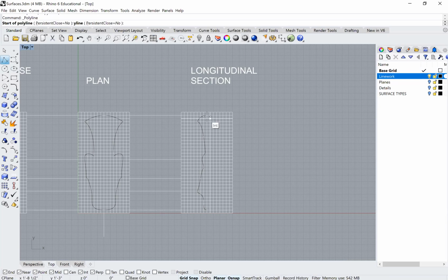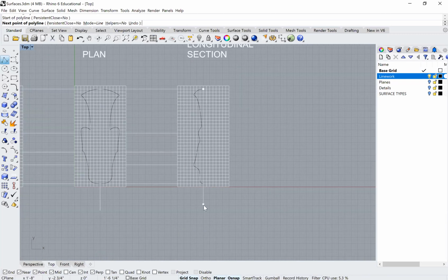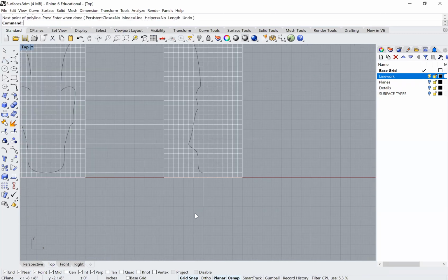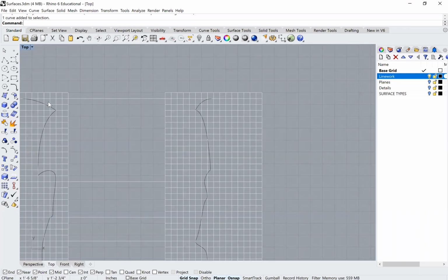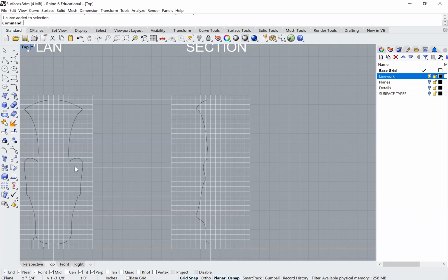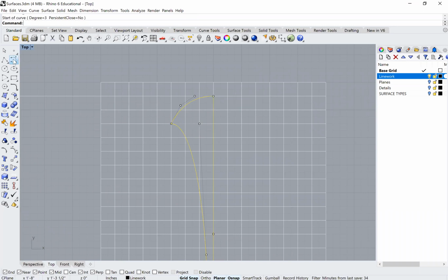And I created a new base, which is this line here. So in a sense, this line that I'm just drawing right here delineates the back or the end of my mask. And then in a somewhat similar fashion as this set of lines here, I drew a series of lines, and I'll try to recreate that for part of it here, but essentially I used the spline command, the curve command, to create the curves, right? And you could see I made it out of composite. So that was my first one.